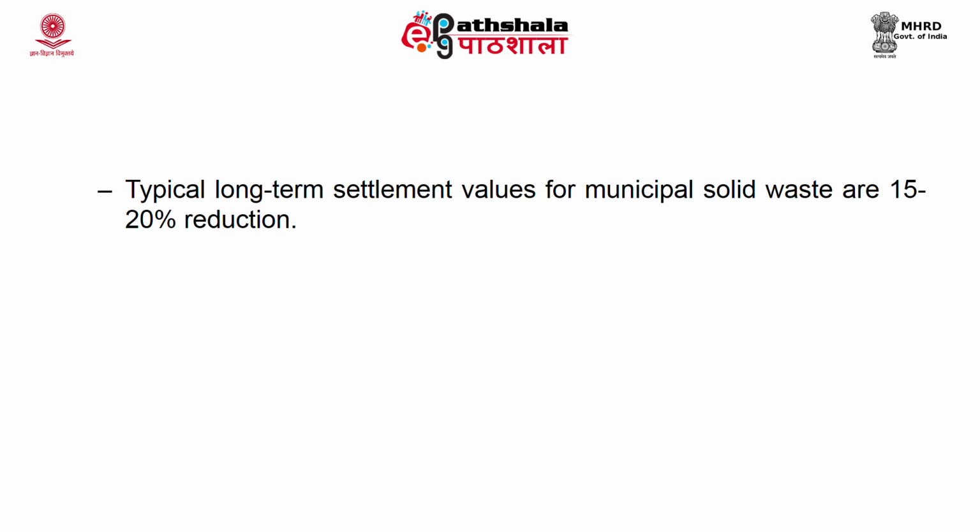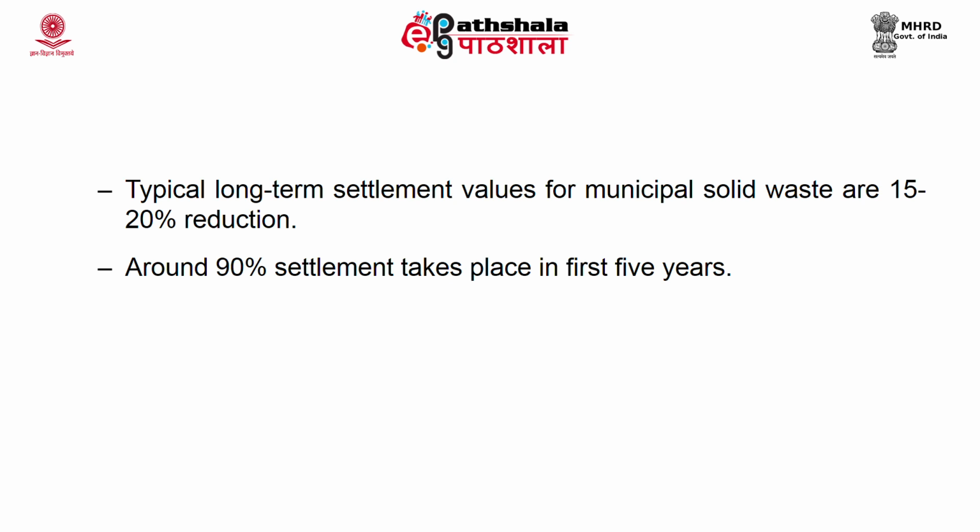The typical long term settlement value for municipal solid waste is 15 to 20% reduction. So, once you load the municipal solid waste into a cell, you can find around 15 to 20% reduction in the long term. Overall, for the first 5 years, almost 90% of the settlement occurs. I am talking about municipal solid waste.